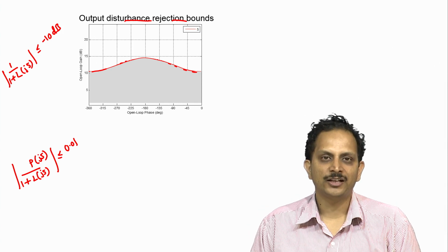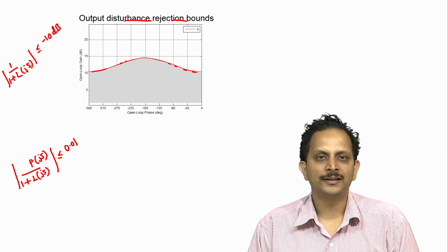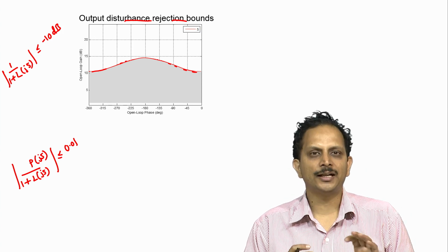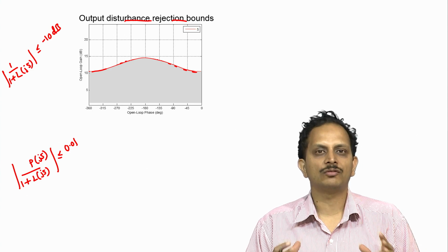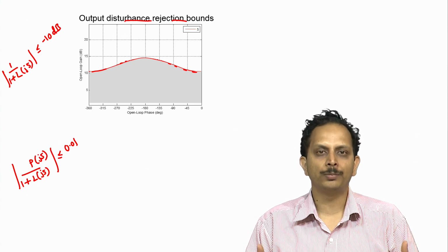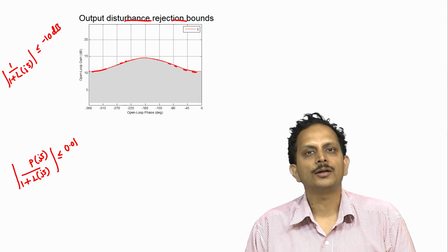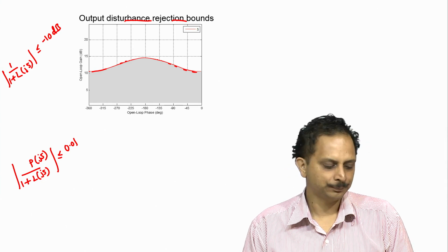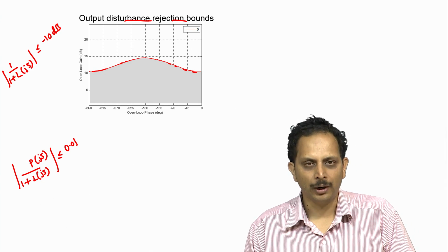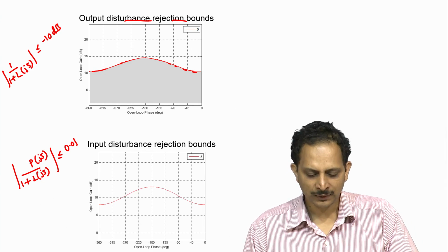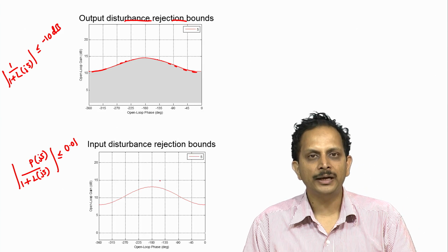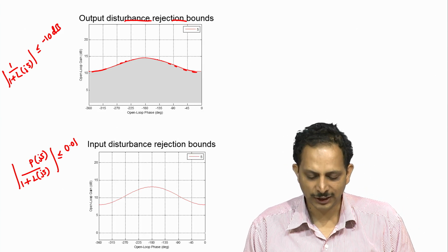Now once again, this is an inequality that represents a certain region in either the Nichols plot or the Nyquist plot, which essentially tells us the permissible values of the magnitude and the phase of the loop gain that allow the inequality to be satisfied. So if we plot the Nichols plot here, this red curve once again indicates the boundary of this permissible region.